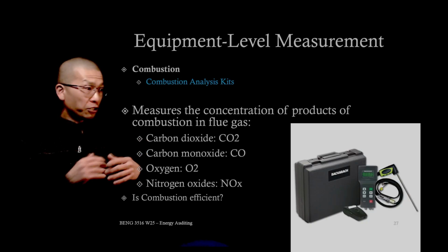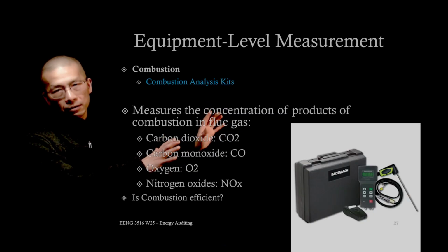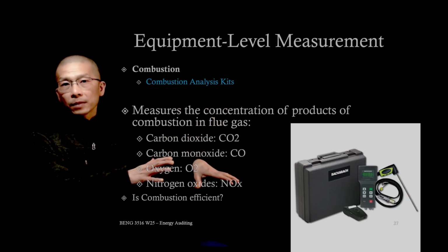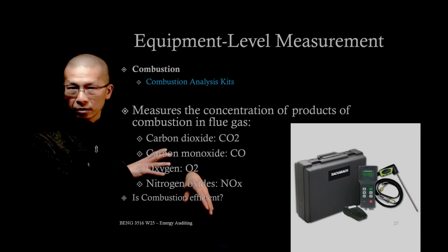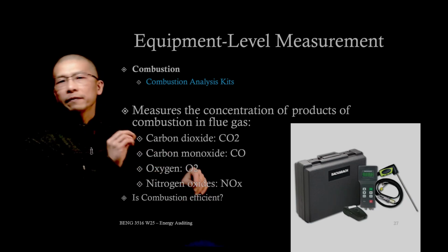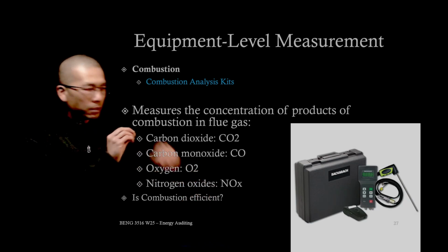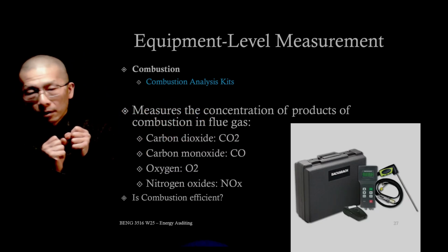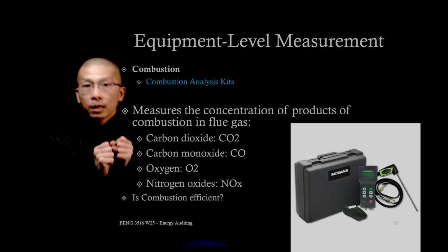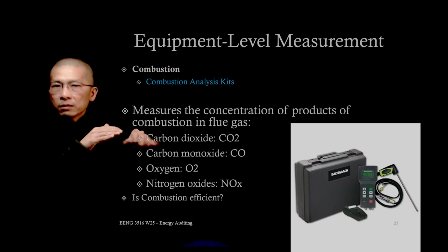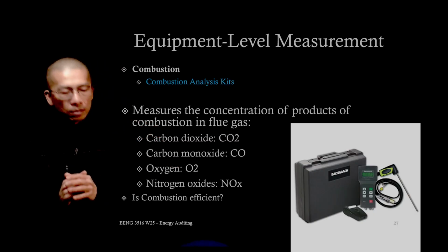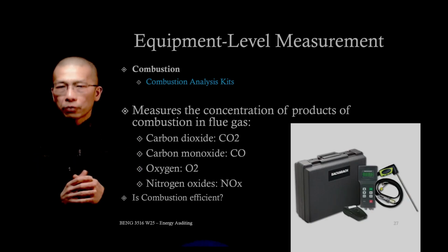You might say, why not just give tons of air? Well, we will actually lower the temperature if there's too much air. You just want the right amount, otherwise the extra air is going to suck the energy from the combustion. So the right ratio is important. How much energy is being wasted, whether harmful emissions are being produced, these are the questions we want to answer.